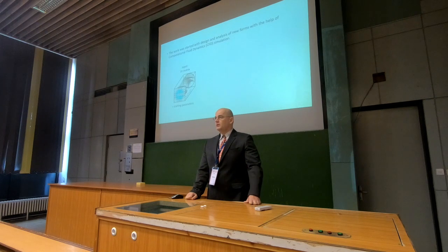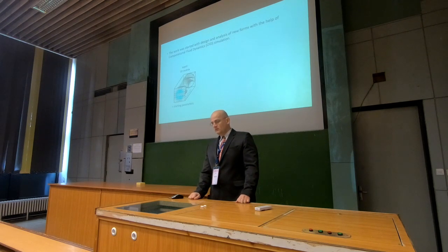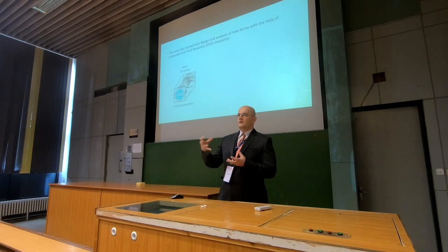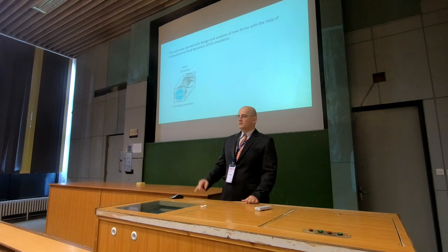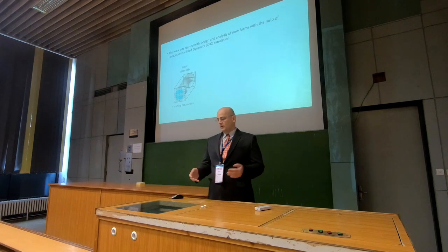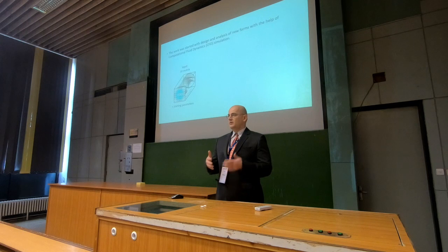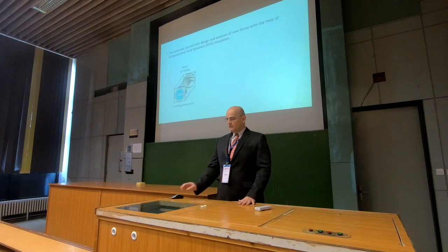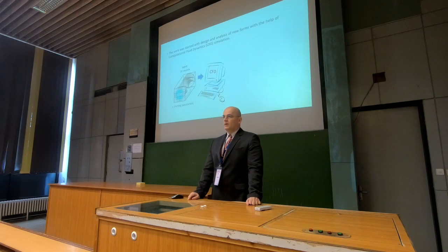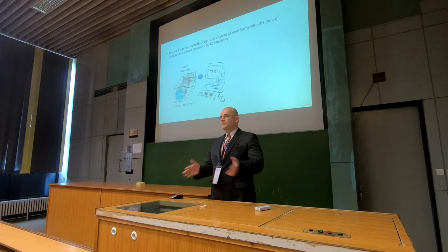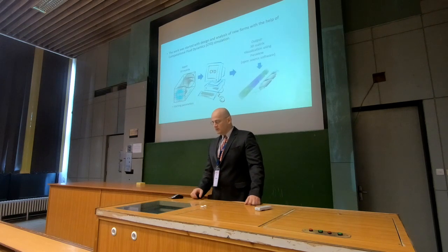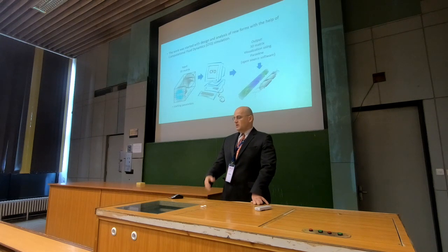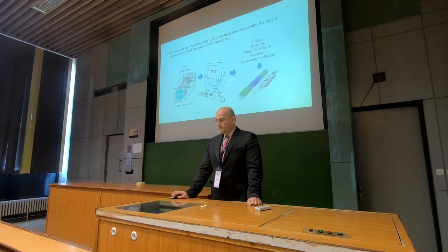The input in the CFD is a 3D matrix where the space around the membrane was divided into particles, and 0 is, for example, where the fluid is present, and 1 where it is not fluid. And also with the starting parameters, this is the input, the CFD calculates the position after 5 or 10 seconds, and the result, the output, is also a 3D matrix, which can be, for example, visualized using ParaView. It is very popular open source software for these purposes.